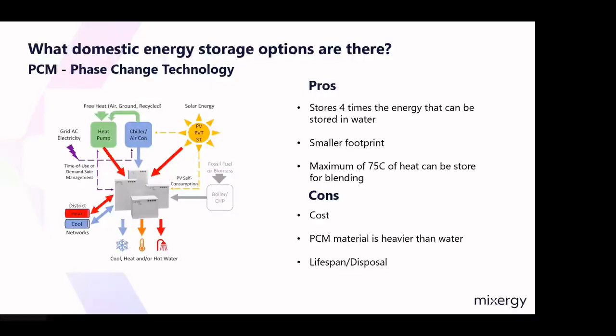Some of the cons: PCM material is more expensive than traditional hot water, and it's a lot heavier, and weight can be a factor during a build and in retrofit locations. The lifespan of a PCM is still to be proven over a longer period of time. There are lots of estimates, but we've seen hot water generation the traditional way for nearly 200 years. But if we look at the lifespan, it's still to be seen. We also have to look at the impact of PCM materials on recyclability. Yes, some can go to landfill, but how does that affect future legislation when it comes to embodied carbon?